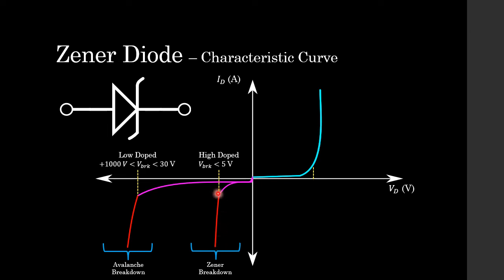Now to me, students, that looks like a very nice regulated source. So our Zener diode can simply act as a 5 volt source, which will remain at 5 volts, but still allow some current to flow through. And that's really the application of a Zener diode, as you'll see in future lectures: it's used to make voltage regulators. But now what does the Zener diode construction look like, and how does the Zener breakdown effect actually take place?